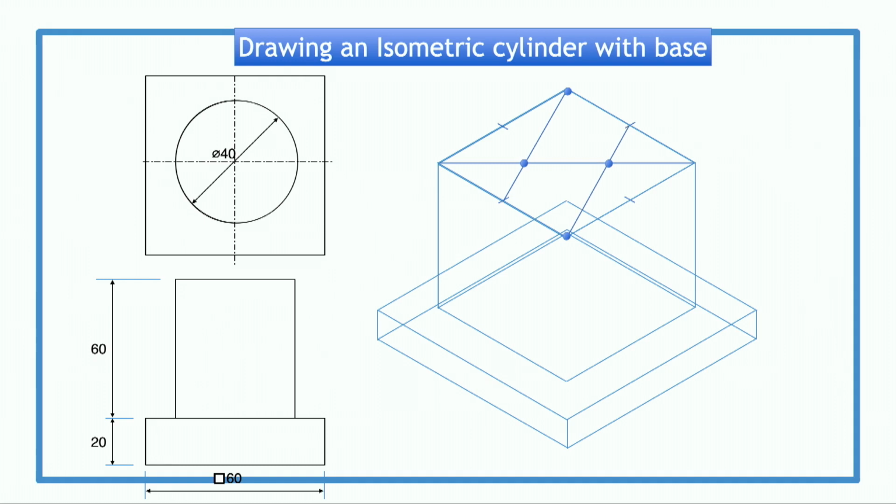Once the centers have been located, we locate the radii needed for the first arc, taking from the center located. The radius goes to the midpoint of the side of the top. Our compasses are set to the required radius and we obtain our first quarter circle. We then move to the opposite center and draw our next quarter circle.